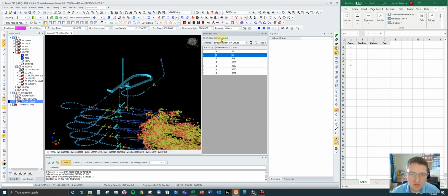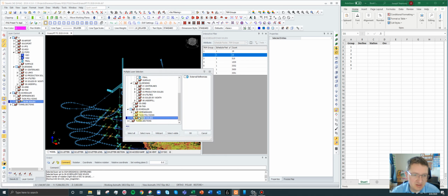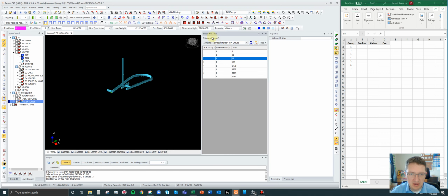It's only filtering one layer. To get it to filter both layers, you come in here, hit tools, hit select layers, and see how it only has one check right here? We need to do 2, center lines, this one. Now we have 2 layers. Hit OK, and see how this says 2 layers selected?